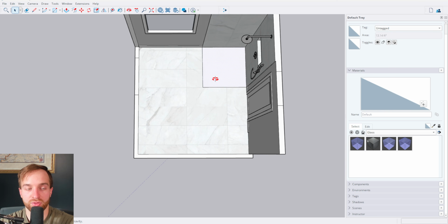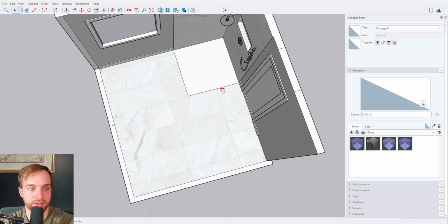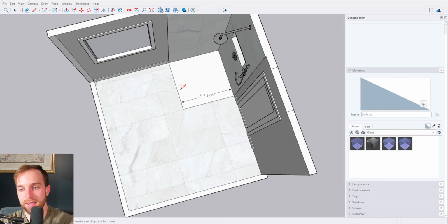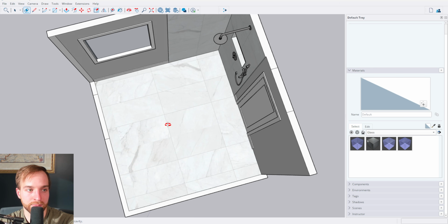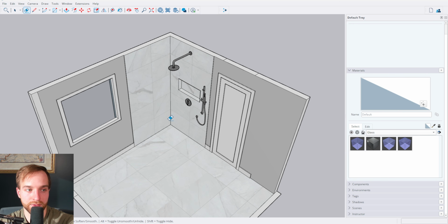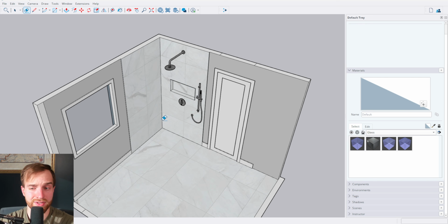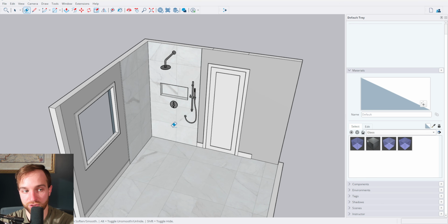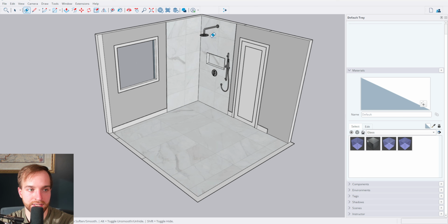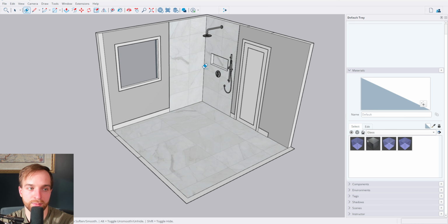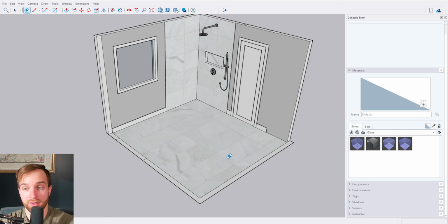For our shower pan, if we're using a prefab shower pan, I can kind of look at this, right? 44 inches, give or take. I know that Schluter, for example, makes a 48 by 48 inch shower pan, so I can get that. I know that for waterproofing panels, this is less than 4 feet. This is 8 feet. So let's say I was using a foam board system, I only need 2 pieces of paneling to do these 2 walls. I know my niche size, I need a niche for that, right? So I can start looking at this and getting all sorts of different numbers, figure out my casing, my baseboard, all of that stuff. And this just makes it really simple and easy to do so.